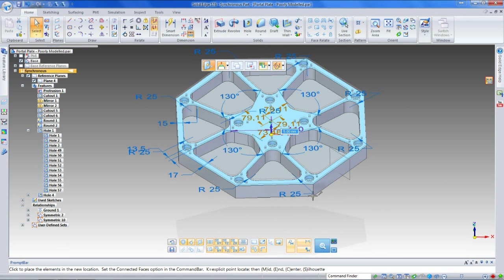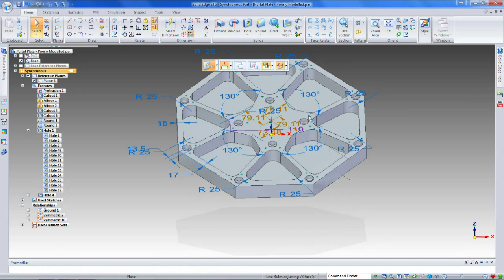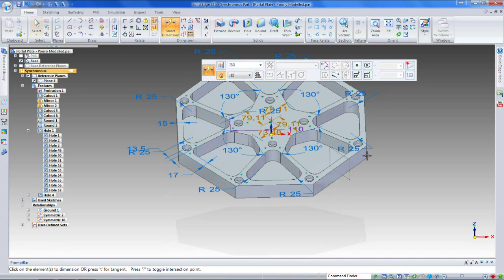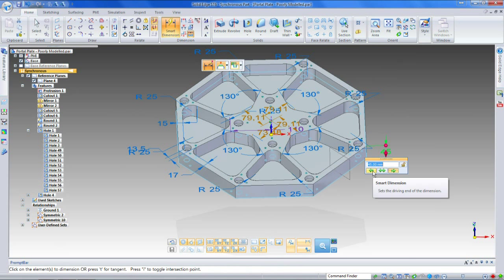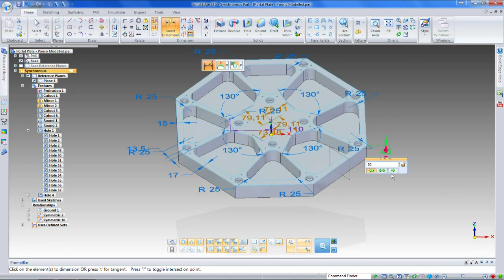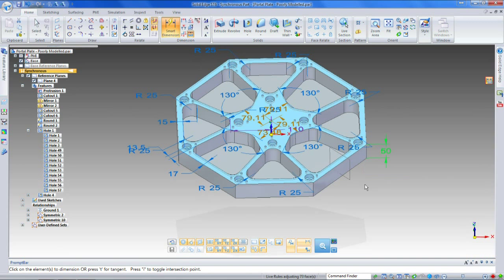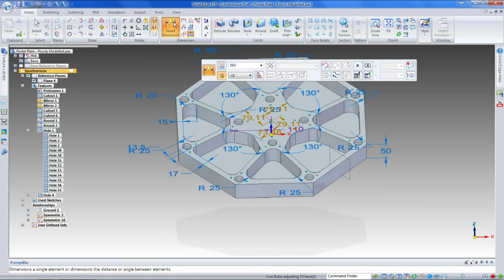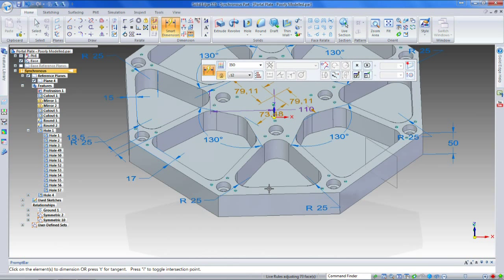I'm just moving the top face so it's 45 millimeters from the bottom face. That's one way of setting the thickness. Now I can also set the thickness just by typing in a value. I can change which face I want to move when I make an edit, and then I can just key in a value. That's another way of making the same change. And I'll just put the dimension in.